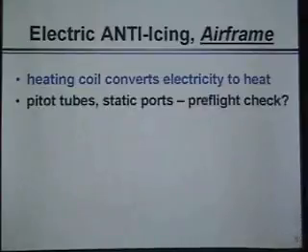Now, you want to check the operation of pitot tubes, and when you start flying an airplane that can go into known icing conditions, you're also going to have heated static ports. The best way to check if it's really working well is not to wrap your lips around it and see if the skin on your lips comes off. And it's not even to touch it with your hand. It's to look at the ammeter.